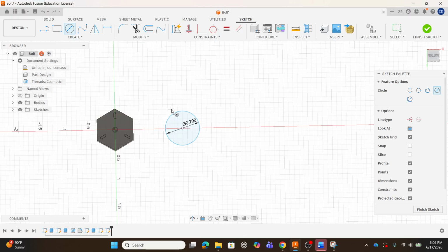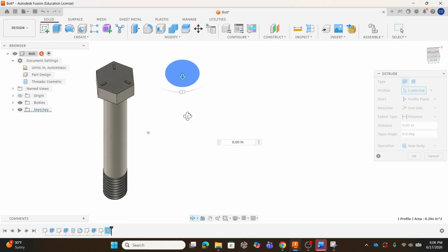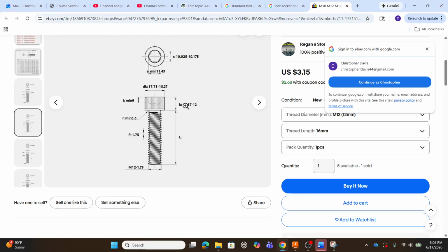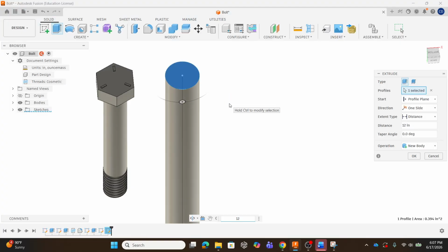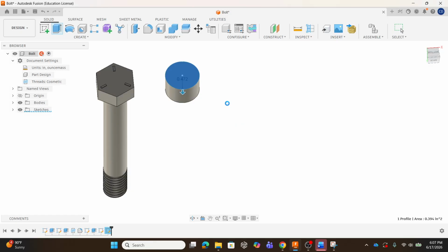So what we're going to do now is extrude it. We're going to hit the letter E, and we're going to extrude down. And we'll just call it 12. So again, we'll type in 12, and then mm. So now I hit 12 space mm. You need the space between it, and that's going to create a millimeter again. Notice it's giving me a standard depth.